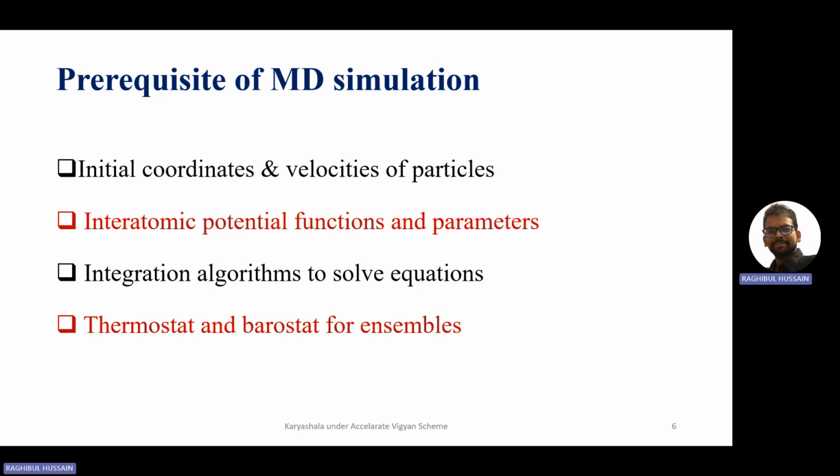So there should be some preventive mechanism where the excess pressure is adjusted. For the pressure cooker, the excess pressure is released to the atmosphere. In simulation, we don't have an atmosphere. It's a computer code, so we need to put in some additional mechanism which will absorb the excess pressure. That's why we call it the barostat.